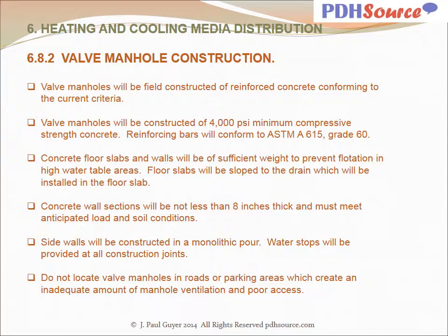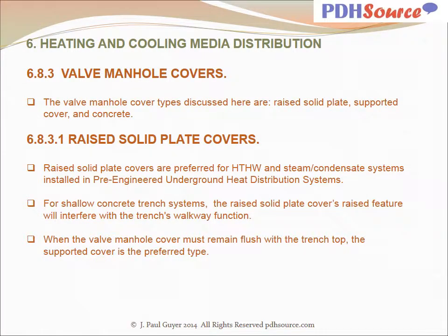Do not locate valve manholes in roads or parking areas, which create an inadequate amount of manhole ventilation and poor access. Valve manhole cover types discussed are raised solid plate, supported cover, and concrete. Raised solid plate covers are preferred for high temperature hot water and steam condensate systems installed in pre-engineered underground heat distribution systems. For shallow concrete trench systems, the raised solid plate cover's raised feature will interfere with the trench's walkway function. When the valve manhole cover must remain flush with the trench top, the supported cover is the preferred type.